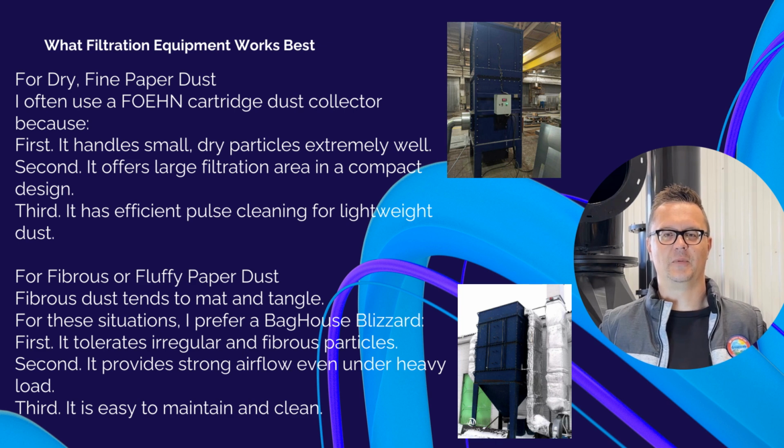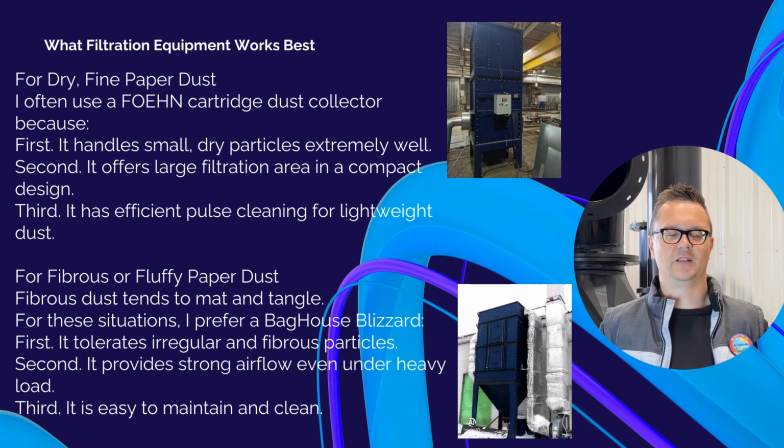Because paper dust can be combustible, I often add, first, explosion vents sized for the collector. Second, anti-static filter bags or cartridges. Third, proper grounding and bonding of all equipment. Fourth, a spark detection or spark arrestor system for shredders. These additions ensure safety and compliance.